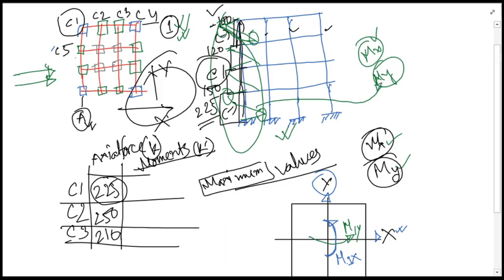And similarly, if you draw the A frame bending moment diagram for the C1 column, you will be getting the column bending moment for the lateral load in this direction, either in this direction or that direction. For each direction you will be drawing this, if not the symmetric view of this building, then for all four directions you will be getting the values, and whichever direction is governing, that value you will be taking into account.